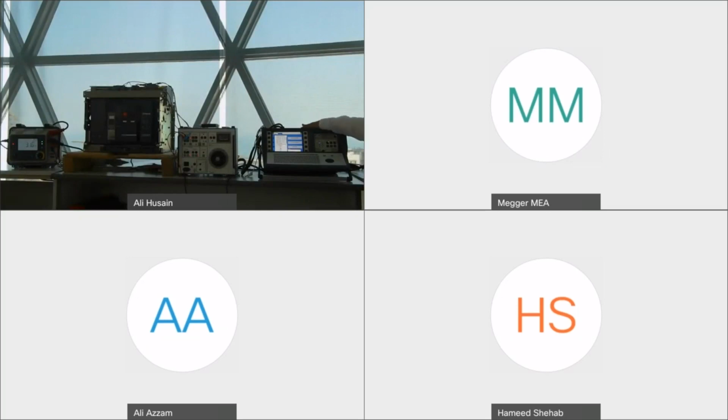Okay, so I have here the TM1800. It's basically connecting 3 timing channels for phase A, phase B, and phase C, or RYB basically, and some control circuit. I have the trip and close. I will show all the connections on the front screen of the device itself.